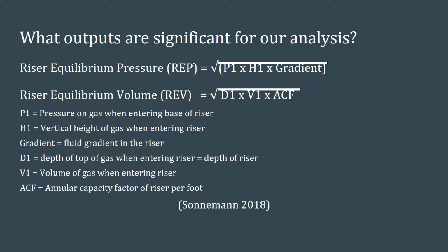The velocity of the gas at the outlet will also be noted, because it may be that the gas is reaching supersonic speeds by the time it exits the riser, which would provide an explanation as to why the simplified models, such as Boyle's law, do not work.